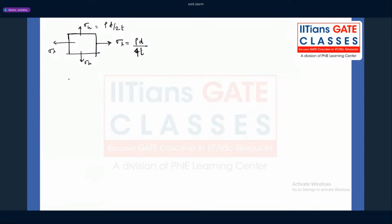Out of these, what is the maximum value? The maximum value is the hoop stress, right? And if you compare PD over 2T with the maximum allowable normal stress, that means this PD by 2T should be less than or equal to this value.